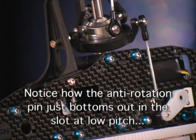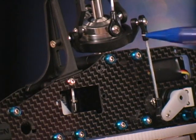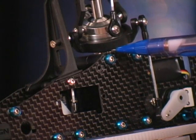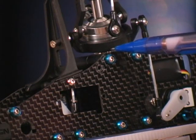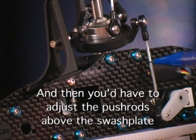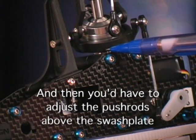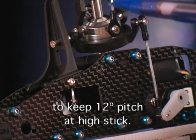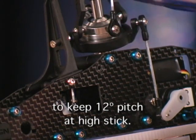Ooh, and that is really close. We're looking at maybe, what, a half of a millimeter there. I probably won't change anything, but if you wanted to maximize negative and positive throw, you'd adjust all three push rods, maybe a half a turn, one full turn, to bring the swash plate right down to the top of the bearing block, and then you'd have maximum travel at the top of the swash plate throw.